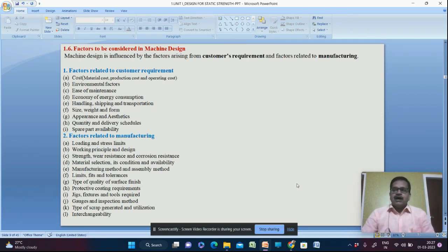So they are having the same motion as that of the shaft. This is the shaft. Over the shaft we have a pulley. So the pulley cannot go around the shaft. Along with the shaft, it has to rotate. So therefore, there must be a fit between the pulley and the shaft so that there is no relative motion.